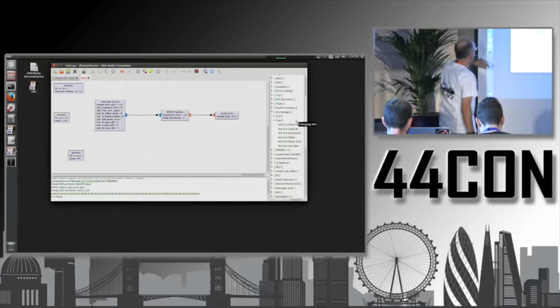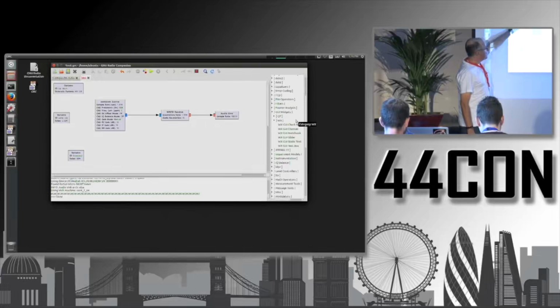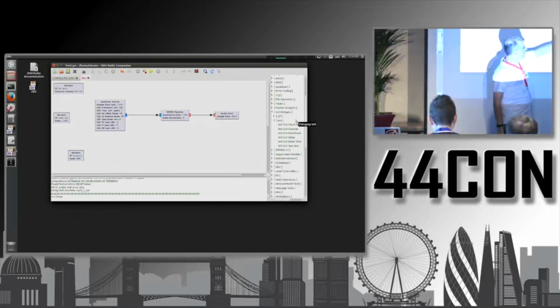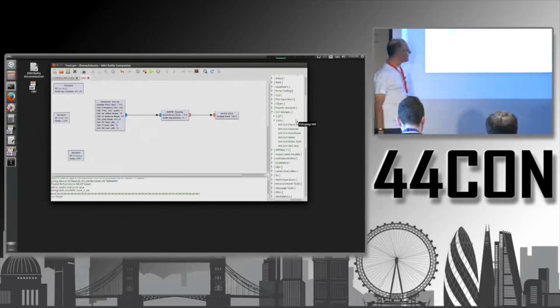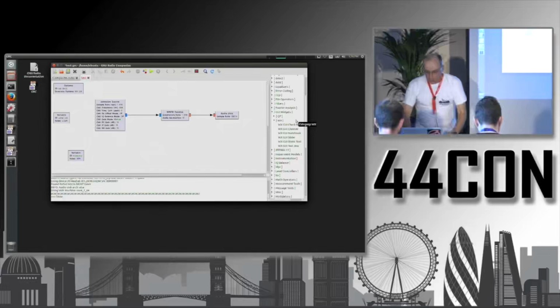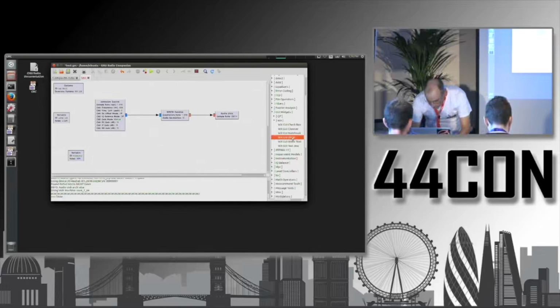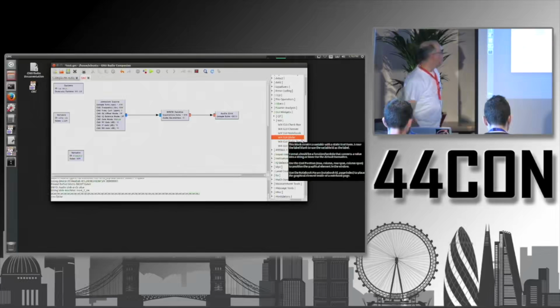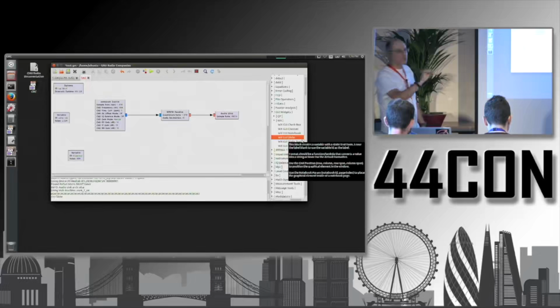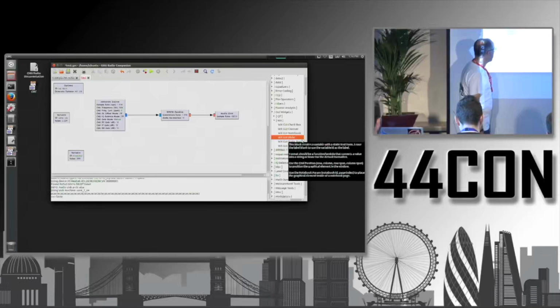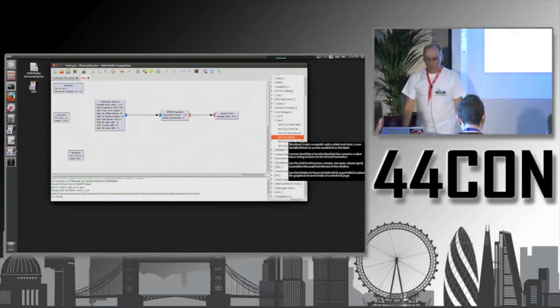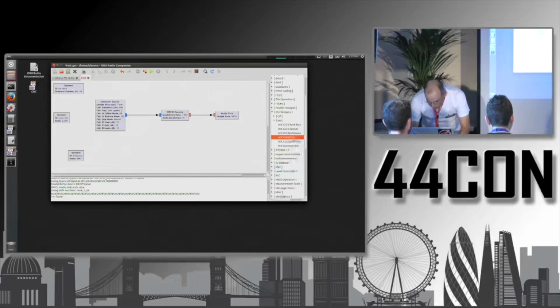So remember we selected WX GUI, so drill down to WX, because those are the components that we are going to use. And what I'm going to use here is the WX GUI slider. That gives me a slider that I can use. So you can drag this onto the diagram.